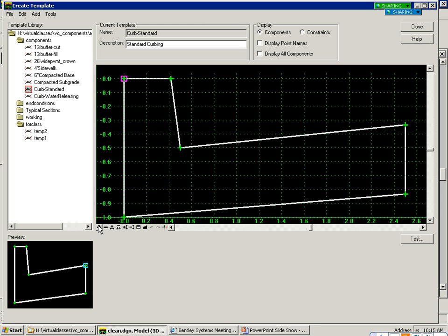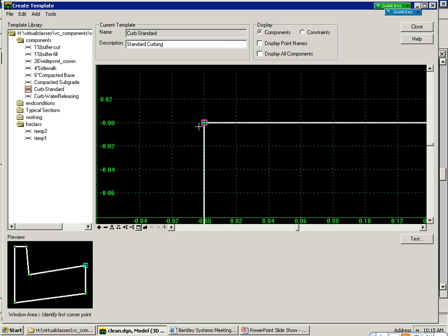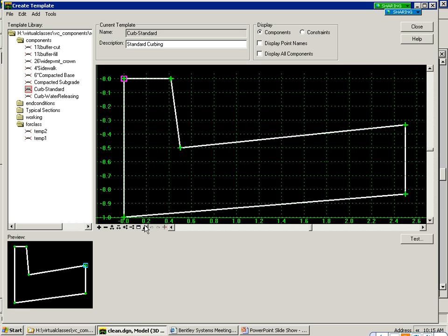And in the lower left pane, these are the view things, very similar to MicroStation itself. Like here's the window area. See the tooltips pop up. Here's where you can do the different zooms. So you can zoom in and zoom out. You can zoom in the X or Y direction to change the scale. If I pick a thing like this window area and I come up here, it takes me there. If I hit the fit, just like in MicroStation, there's everything, okay? Very simple. Okay, so let's talk about what we're doing here.